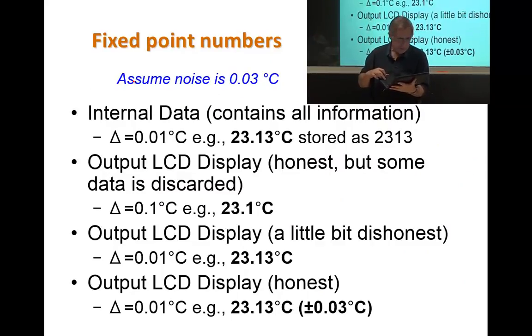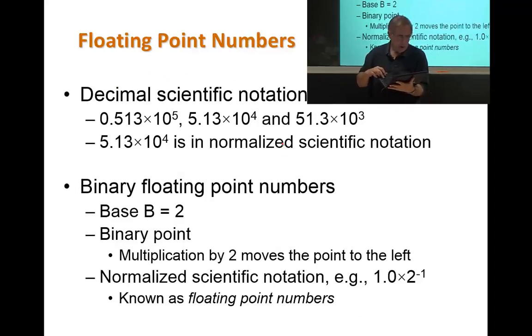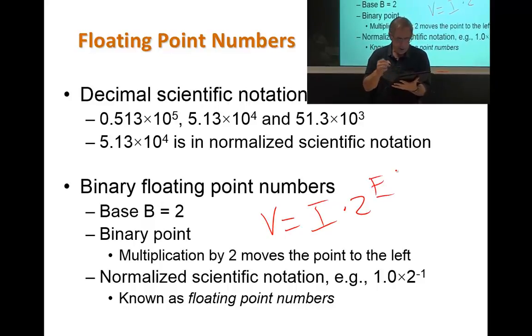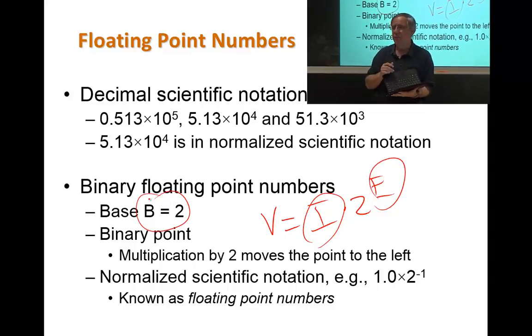That's your lab. Again, because it's decimal fixed point. All right. That was decimal fixed point. That was fixed point. What's our alternative? And that's floating point. Floating point, we're basically going to, the value of the number is going to be an integer times 2 to the e. And I'm going to remember both the integer and the exponent. And the base, I don't know of any floating point hardware that use anything other than base 2.